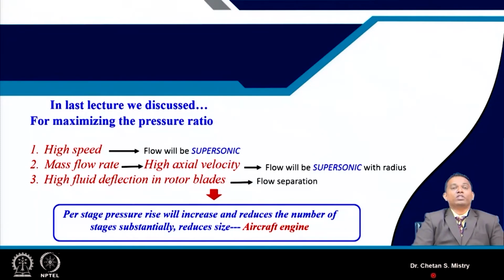Now, by any means, what we are looking for is a larger or higher per stage pressure rise in order to reduce the number of stages, in order to achieve compact, lightweight and fuel efficient engines for future aircraft. So we need to focus our study more towards the development of higher per stage pressure rise, and that is the reason we now need to address the issues related to supersonic flow.